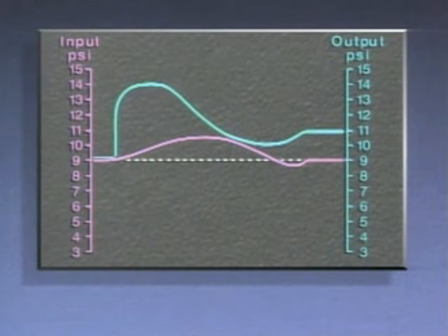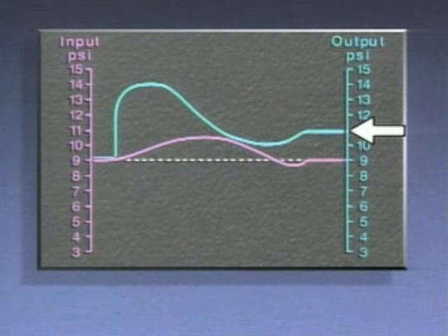As the rate portion of the controller output worked to stabilize the oil temperature, the reset portion of the output worked to return the oil temperature to set point. Soon, the combination of reset and rate control returned the oil temperature to steady state at its original set point. The final output signal also returned to steady state, but at a higher value. The higher output closed the control valve to a new setting to maintain the oil temperature at set point.